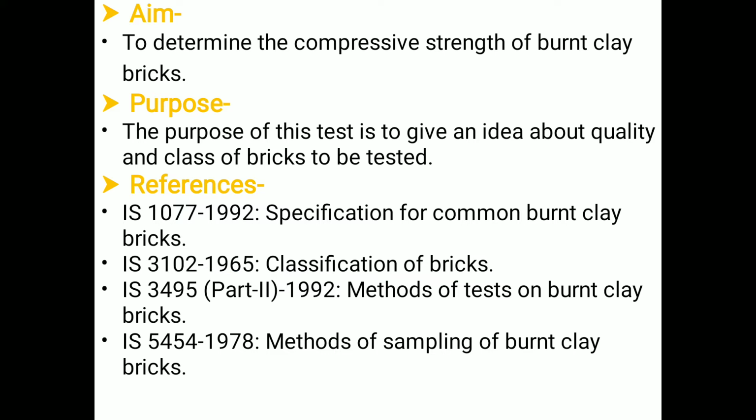The third reference is IS 3495 part 2 1992, which gives the methods of test of burnt clay brick. And the last reference is IS 5454 1978, methods of sampling of burnt clay brick. Those are the references which we have followed for the compression test of the brick.